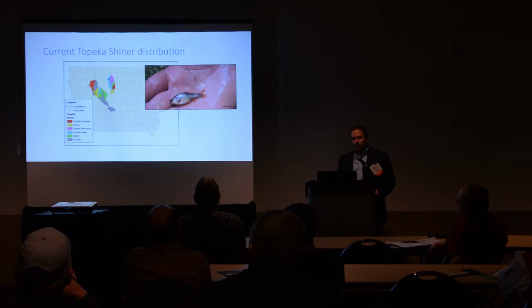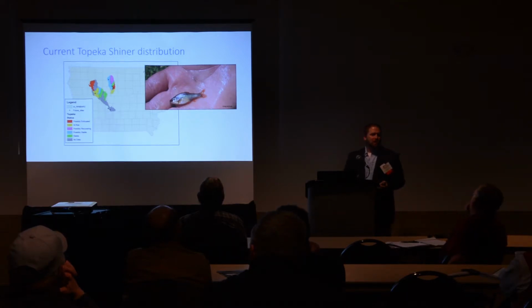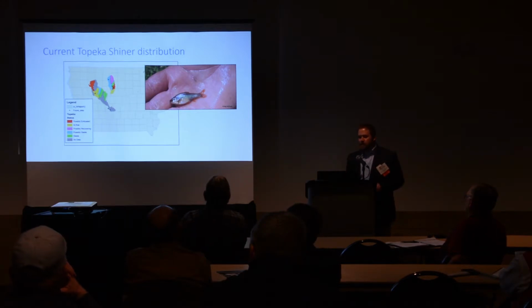We call it a multi-purpose oxbow because they're not designed for 100% nitrate reduction. For that purpose, you really want it to be shallow and wide to get that water warmer, with more interaction with the oxbow bed itself. But we need to have it deep enough at the same time so when these fish come into it, we're not acting as a trap. They come in there during a spring flood, and if that water runs out, they'll die. So we don't want to be installing a bunch of these oxbows to remove nitrogen, then having these fish move in and have a problem there because we're killing off the shiners. The other advantage is that since there's an endangered fish species that this would help, there are a lot of other groups interested in helping to get these practices in the ground.